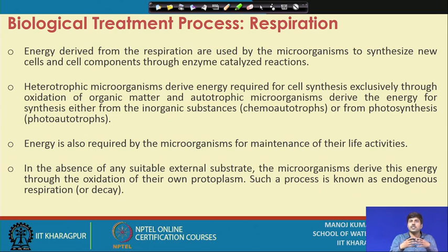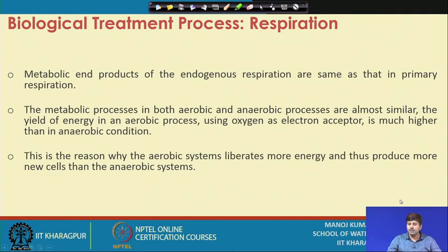Because their protoplasm is oxidized and broken down, the microorganisms are killed in a way, and that is why this process is known as endogenous respiration, or what we typically call decay of microorganisms, leading to negative growth because there is no substrate available.